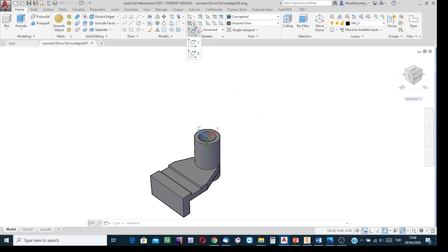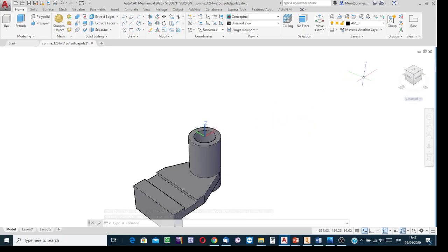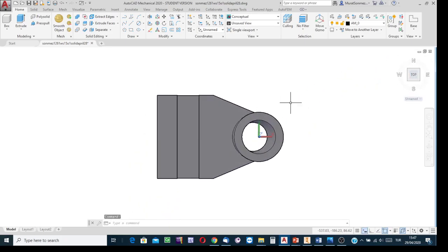Okay, drop this list. This is the multi-optional facility used to rotate the coordinate frame about one of the axes. I know that if I rotate the frame about the x-axis 90 degrees, I can have the XY plane over the surface. So click on this option, to rotate the frame about the x-axis, and write into the box 90 degrees. 90. Press enter. You see now it is okay. The XY plane is coinciding with the surface, the analysis surface.